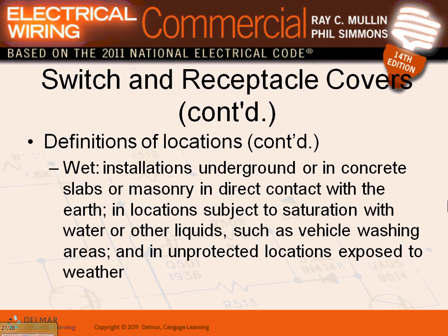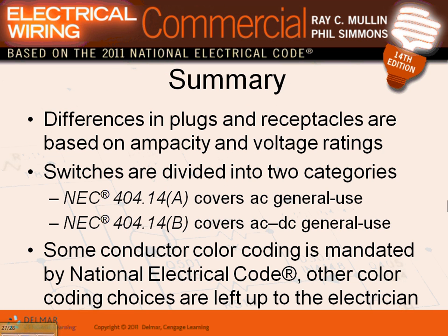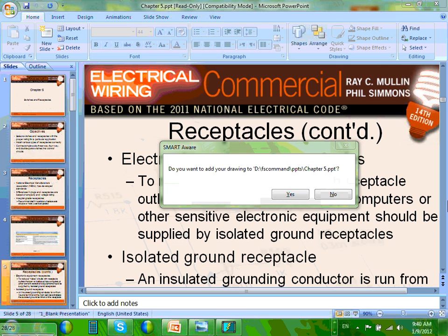So why is wet location important? You have to have GFCI and in-use cover and weatherproof. GFCI, in-use cover and weatherproof. So that's what I have, guys, for you.